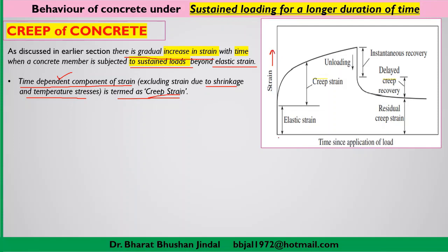Up to this particular limit the load is consistent and the strain up to this limit is known as elastic strain, because it is the elastic part of the curve. This is the strain when the load is within the elastic range.